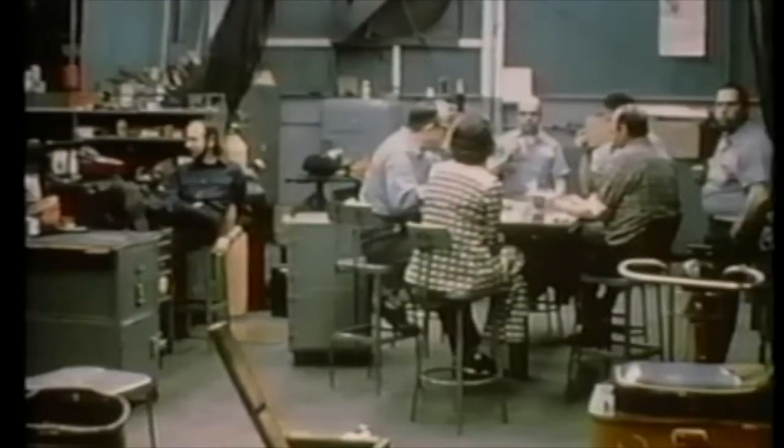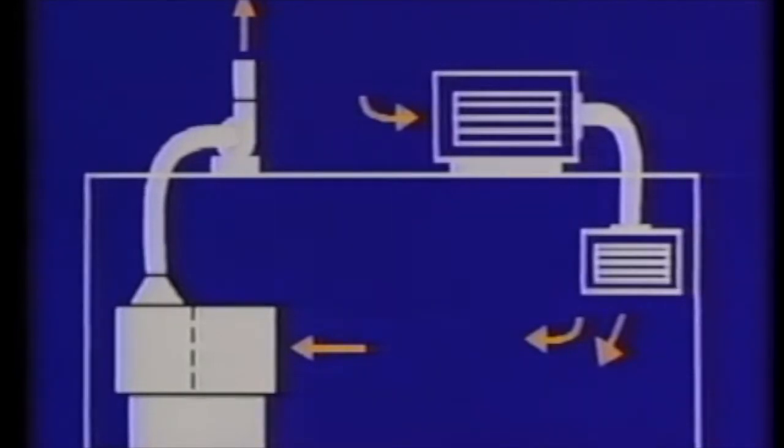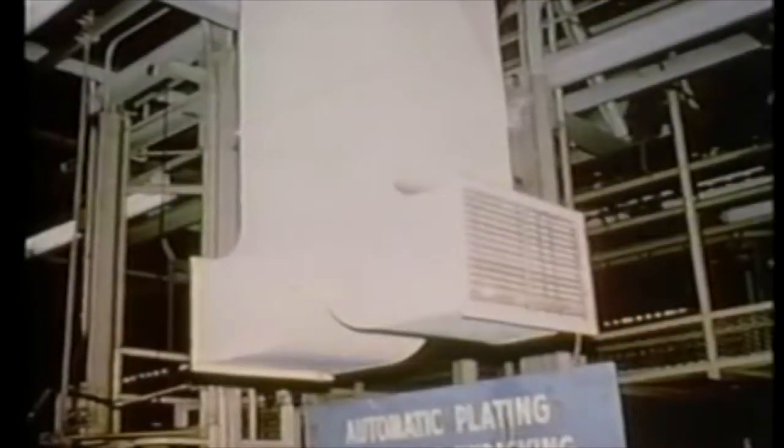Where employees are close to the emission source, local exhaust is usually superior to dilution if it is feasible. Both types of ventilation require tempered, heated or cooled makeup air to replace air exhausted through the ventilation system. Think about it. Air removed must always be replaced. It is best to do this through designed and installed makeup air systems.